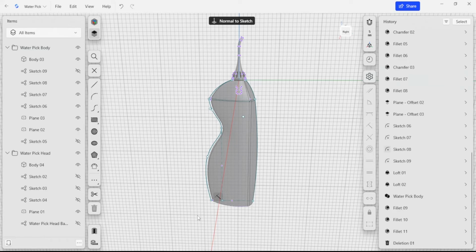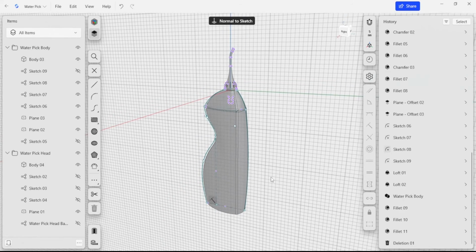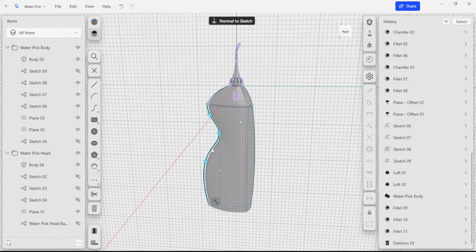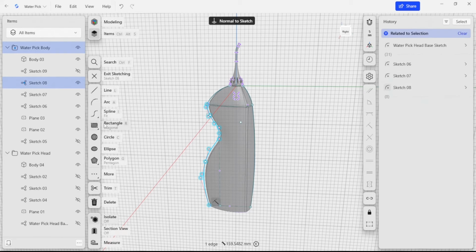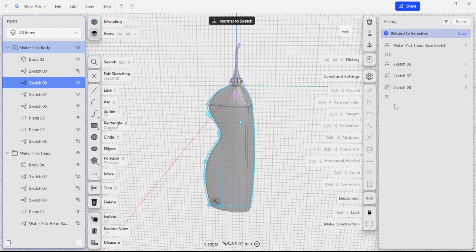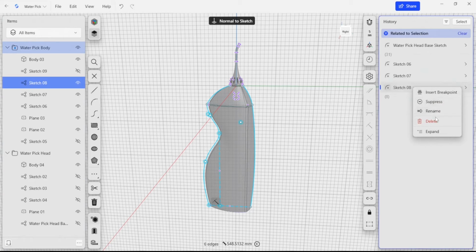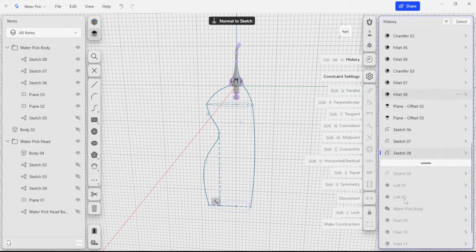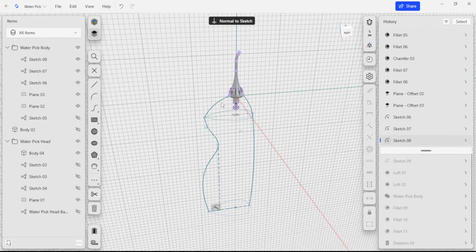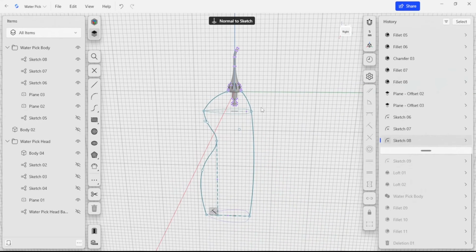Relating to that, I'd say to try to keep sketches focusing on one view, so all the features that are being created that are relevant to one another are in the same sketch, and that way you can continuously reference them. For example, I know that the top section that we use to make the body is also referencing the same sketch that's on the side. So even though we made two separate bodies, we used the same sketches to make those, and that just helps things stay consistent.